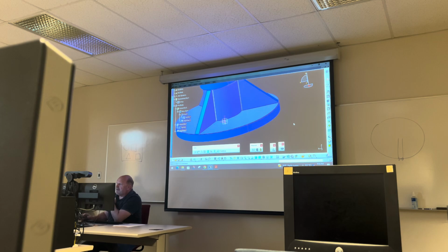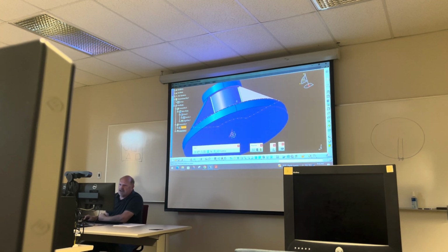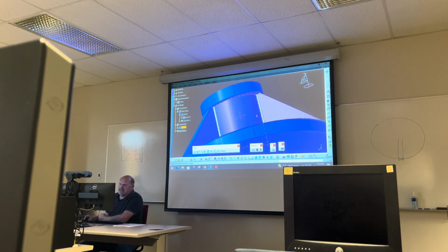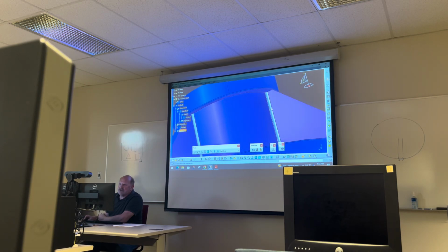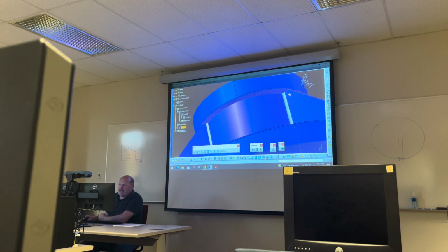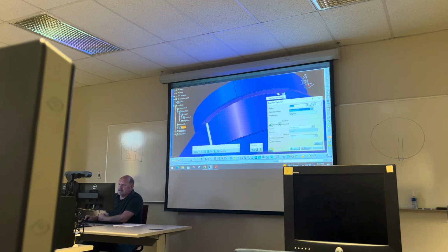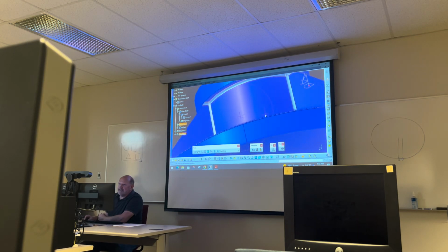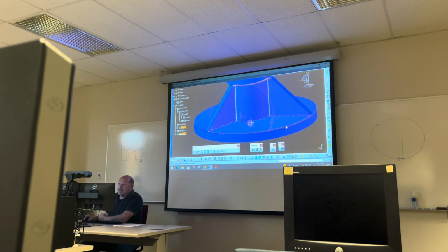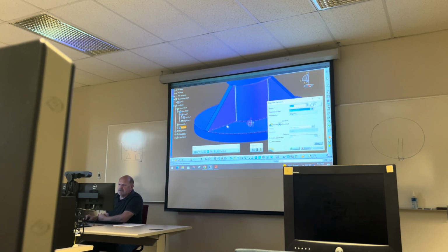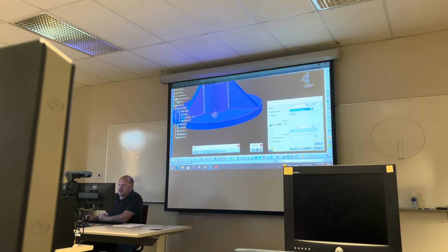Okay, so a lot of people say, well, where do I start? Well, it's either horizontal or vertical, depending on the geometry of the part. So I put those two in, and I'm going to look at underneath here, because what that did is, when I did these two verticals, it defined the track, or the last fillet for this one up here. So I'm going to put that one in. And that gives me that tie-in with all that. And then I'm going to do the one down here at the bottom. And if I look at it, that's what I wanted it to do.